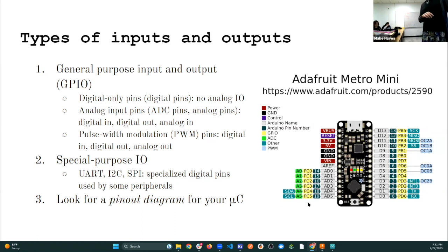What that means is that if I'm using this as an analog pin, whatever thing needs to know about it is going to be asking, what's the analog pin that you're using? And I'm going to tell it something like A0 or A3 or A5. If I'm using this as a digital pin, then the number I'm going to use for it is between 14 and 19. So depending on what you're using the pin for, it has a different name, but it ends up being the same physical pin on the board.